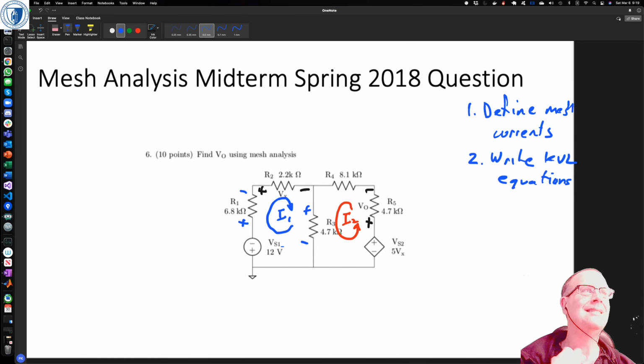If that's the case, why is I1 clockwise? Because the orientation of that voltage source is opposite from the one of I2. Right. There's always a contention between the passive sign convention and keeping the signs correct, and what we know about the way electrons flow.